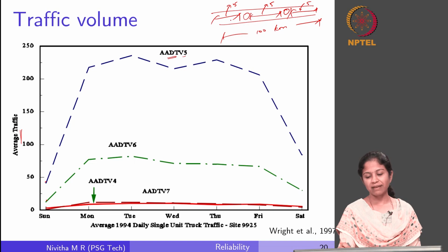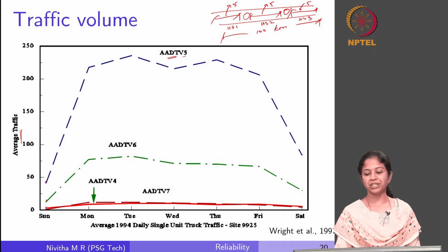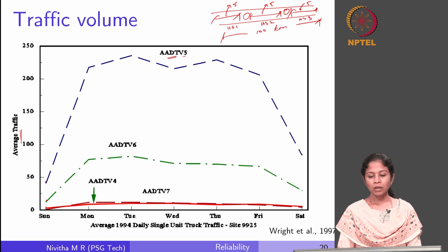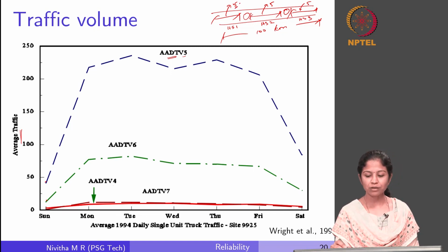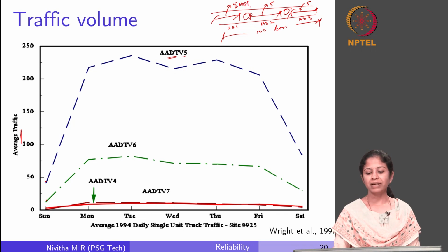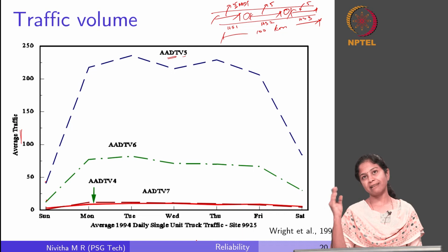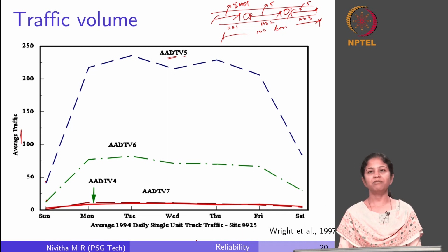So, let us say we do different design procedures for this homogeneous section 1, this section 2 and this homogeneous section 3. Okay. So now if I get 5 values here, and let us say there is some degree of variability in all these 5 AADT values, which AADT among these 5 values will I use for design? Will I use an average value, or will I take the maximum value or minimum value, right?